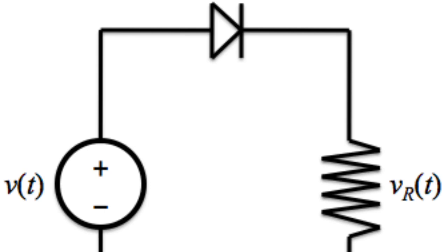The second requirement is that the bias voltage must be greater than the barrier potential. Mostly, the barrier potential for germanium is 0.3 volt and for silicon is 0.7 volt. And for the reverse bias, my friend Chuah will explain more about it.